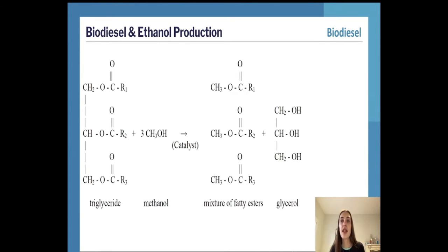If the feedstock has a high acid content, acid catalyzed esterification can be used to react the fatty acids with the alcohol to produce biodiesel. But we can also use other methods such as fixed bed reactors, supercritical reactors, or ultrasonic reactors to forego or decrease the use of catalysts, so the base catalyzed or acid catalyzed method, but we won't discuss those methods today.